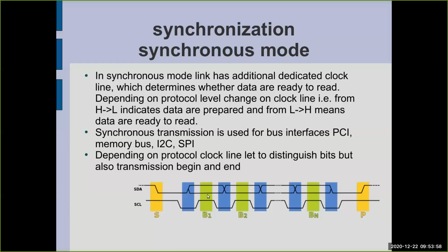In this case, you can see that the read command is on the rising edge, but there are some solutions which operate on two edges, or they operate on levels. It depends on implementation. So it seems that it is a very efficient solution which lets us avoid synchronization problems, and it seems that it should work even for very high-speed interfaces.